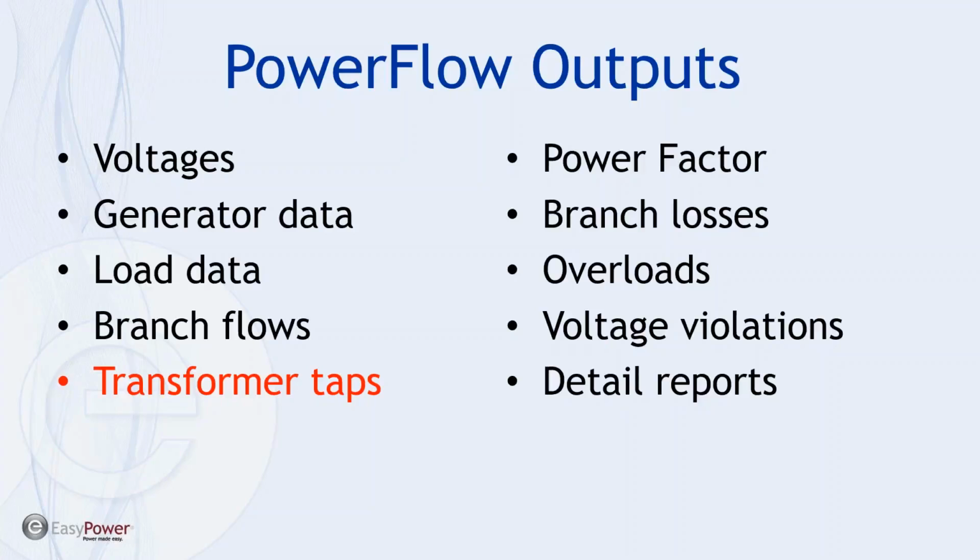One other factor that's particularly useful comes up almost without emphasizing it, and that's the ability, when we're doing a new design or an extension to a plant, to see the effect and the need to have transformer taps to minimize the power drop or the voltage drop coming into the system.